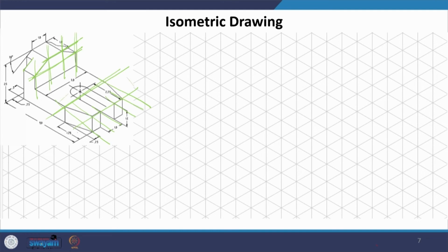Now, it is only for this one, we also have the reference planes for this part as well. So, this is what we are going to be looking at. Now, see here we have an inclined surface, but then it is going and becoming vertical, which is what we saw here. It is not a continuous inclined surface, it is broken, and here we have taken a vertical at the back. We will arrive at all of these by drawing the reference planes, but the correct reference planes, which is our task to identify when we are converting this iso to ortho.